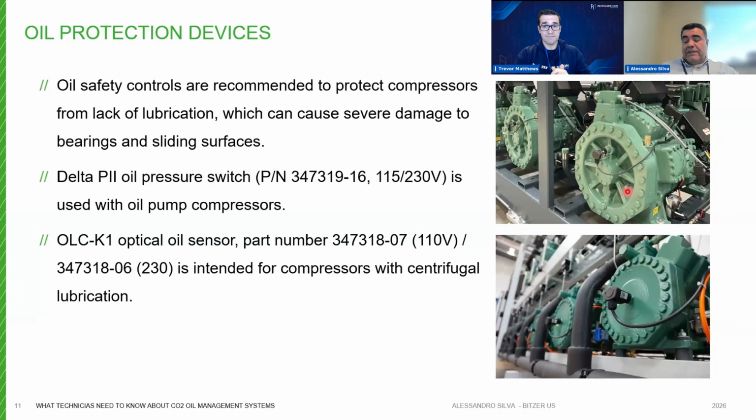Yes, this is a good point. For CO2 applications, we always recommend the proper tools and proper hoses, never mixing up hoses for standard refrigerants with the CO2 refrigeration system. So it's better not to mix the hoses. Always use the proper tool for that.